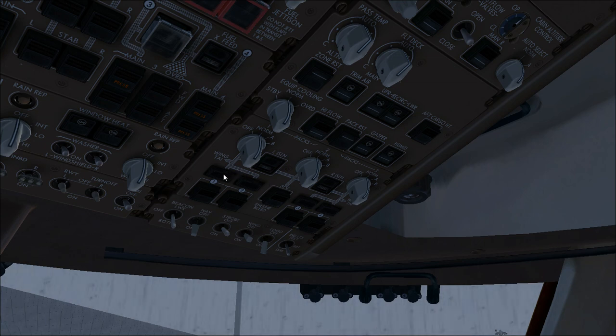Oh, sorry, it's different. Engine bleed air system fault lights are those four lights here. They are extinguished anyway. EPU bleed air switch on. We can select it on. The EPU is on, and you should hear the sounds coming up. Probably the sound is not so loud in the video because I'm using low sounds to make it possible for you to hear me talking. Now we have the EPU selected. The valve light is off, sorry. Engine bleed air switches are all in on position.